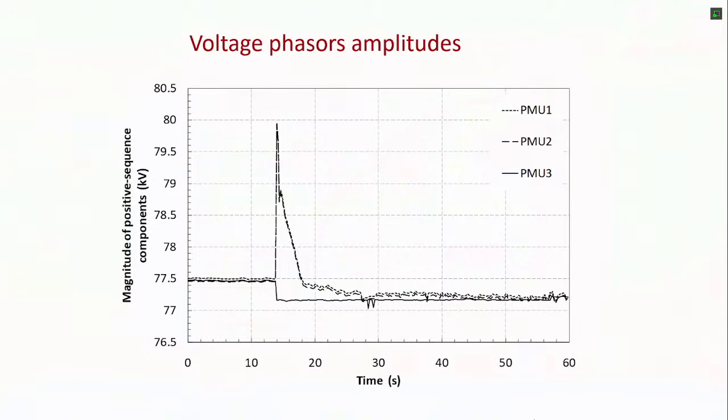You see also here the effect of the excitation system, the control system of the voltage in the power station that keeps the overvoltage. It limits, in a few seconds, less than 10 seconds, the voltage in the distribution network. So the voltage control is probably faster than the frequency control.